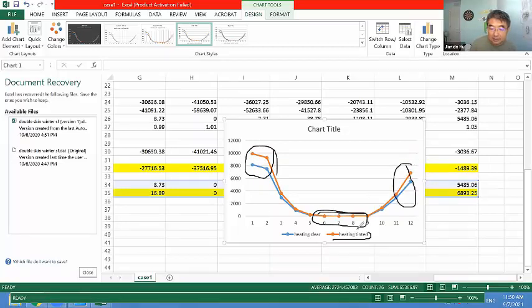So the tinted, which is the orange line, will need higher heating loads. This is the heating sensible loads. That means that if you use tinted glass, you're going to have to heat the building more because you don't have as much solar gain from outside. But the clear glazing here will give you lower heating loads, because it's clear, it's admitting solar gain. You don't have to burn as much energy inside the building to heat to the same temperature. Okay? So that's this.